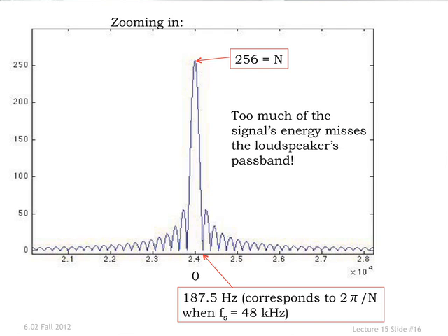So here you now see the full spectral distribution. If you're willing to let your eye interpolate between these samples that I've got, you see the full spectral distribution of that rectangular pulse, a short pulse in time. It's got certainly high DC content, but it's got tremendous frequency distribution all the way out to high frequencies. In fact, all the way to the end, you're still seeing frequency content. It's visible to the eye, all the way out to 24,000 hertz, and you could keep going.